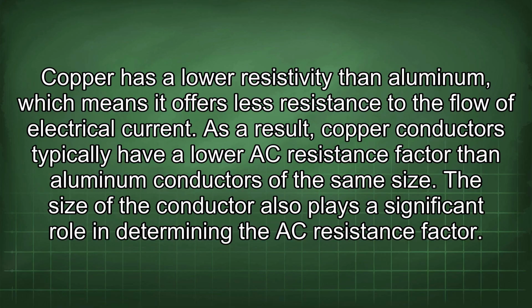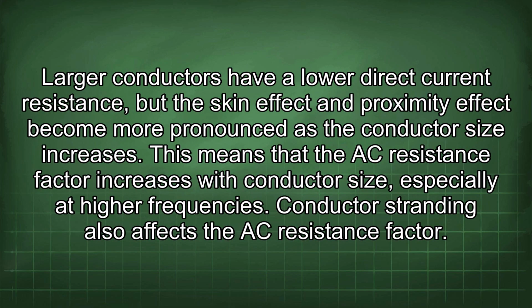The size of the conductor also plays a significant role in determining the AC resistance factor. Larger conductors have a lower direct current resistance, but the skin effect and proximity effect become more pronounced as the conductor size increases. This means that the AC resistance factor increases with conductor size, especially at higher frequencies.